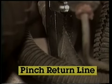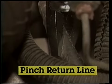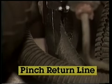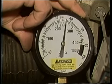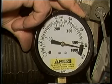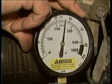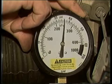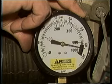When the return line is restricted, fuel pressure should jump up to maximum fuel pump pressure potential. This eliminates the pressure regulator from the system. If your earlier tests showed low pressure, then this high reading would tell you that the pressure regulator must be shunting too much fuel back to the tank and is defective.